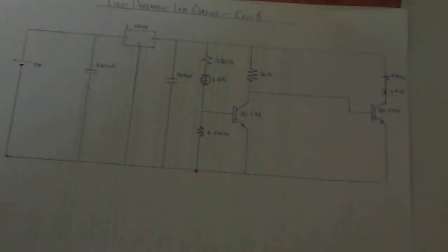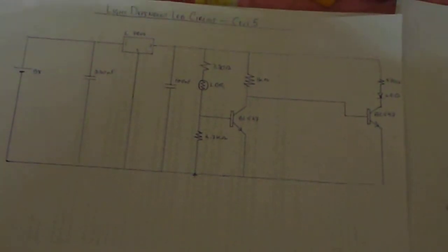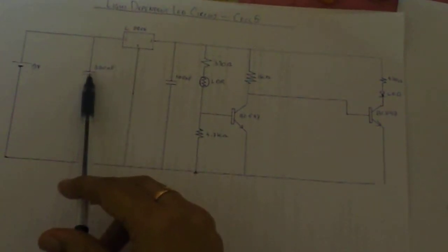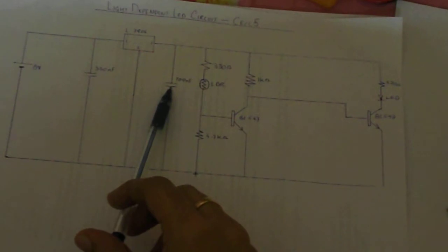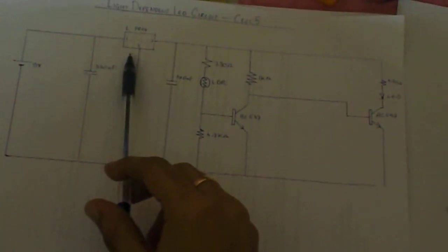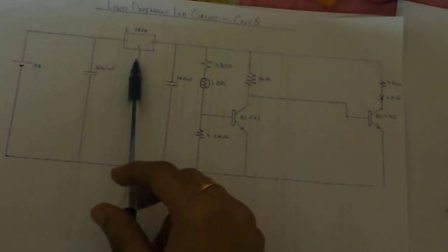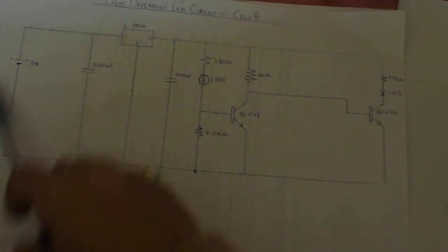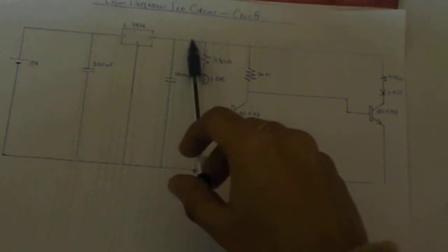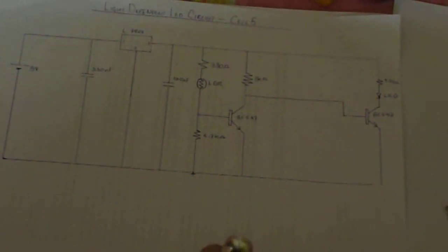Then, with some bit of abstraction, some trial and error, problem solving, I got to know that this combination of capacitors, 330 nanofarad and 100 nanofarad, would work, and this LM7806 has a 6 volt output for 12 or 9 volt inputs. So I use these, and this portion converts 9 volt to 6 volt. And here you have the ground, and between the ground and this portion you have a 6 volt potential difference.